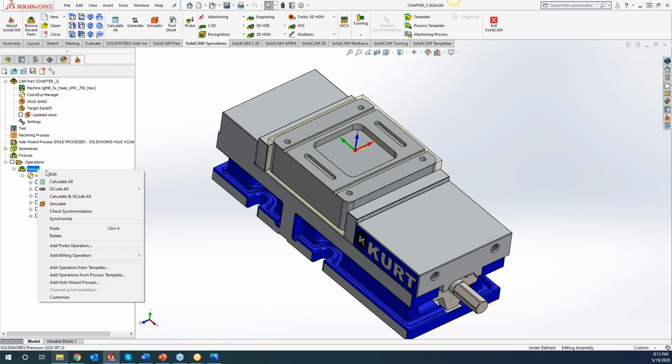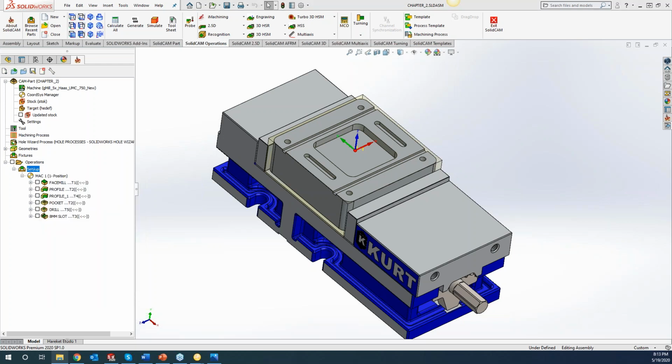Okay, with the CAM temporary folder, does everyone have a good understanding of that? I've got a couple people that don't quite understand it, so I'll go into a little more detail of how the temporary file works. When you're running in compress mode, which is SolidCAM PRZ, it was mostly designed for working on a server.